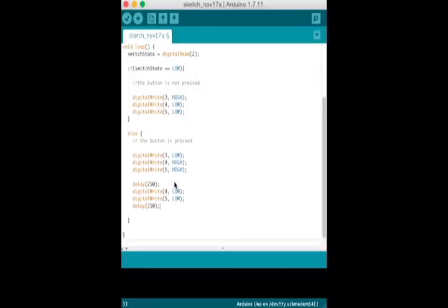I think I've read all that. After setting the LEDs to a certain state, you want the Arduino to pause for a moment before changing them back. If you don't wait, the lights will go back and forth so fast that it will appear as if they are just a little dim, not on and off. This is because the Arduino gets through its loop thousands of times each second, and the LED will be turned on and off quicker than we can perceive. The delay function lets you stop the Arduino from executing anything for a period of time. Delay takes an argument that determines the number of milliseconds before it executes the next set of code. There are 1,000 milliseconds in 1 second, so a delay of 250 will pause for a quarter of a second.